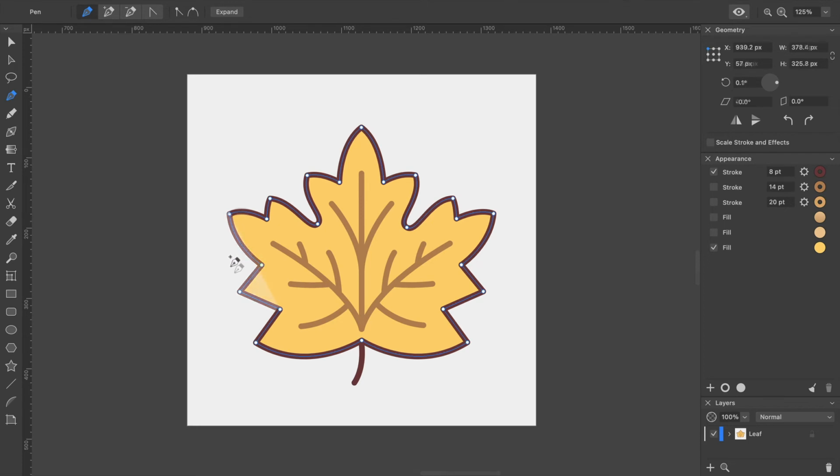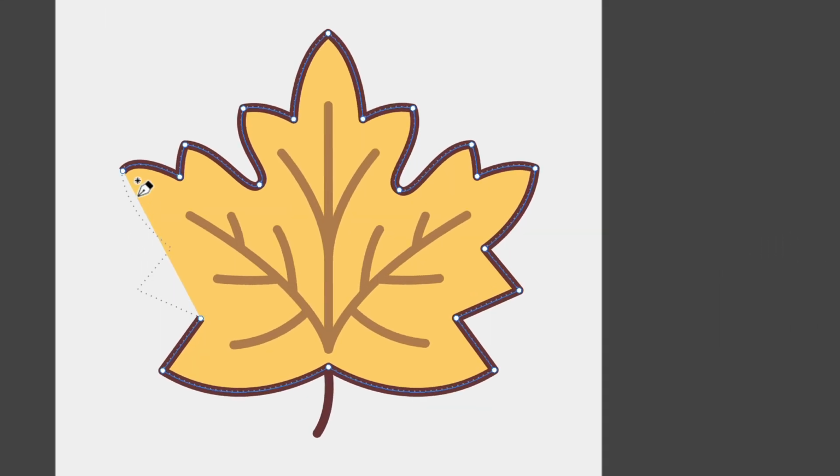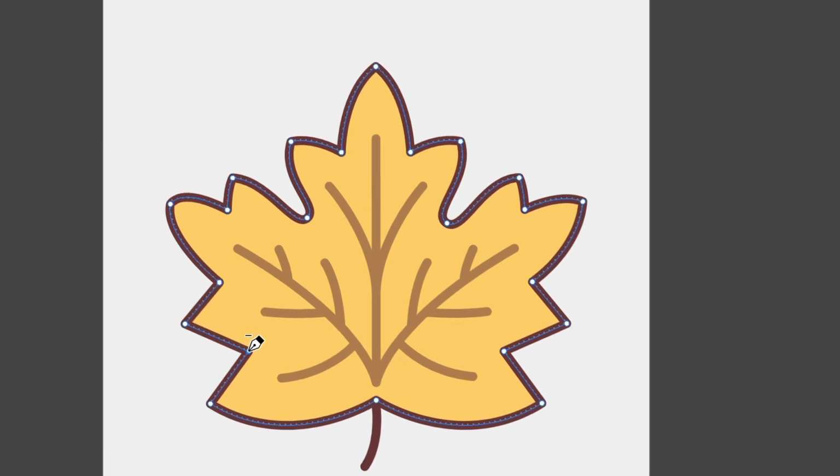If a path is opened and consequently has free ends, you can add more segments to the path or close it. Select the path, switch to the Pen tool, and place the cursor near one of its endpoints. A slash sign in the cursor's icon indicates that you can continue drawing this path. Click on the end point and add another segment or segments. If we bring the cursor to the second end point, a small circle that appears tells us that adding this segment will close the path.